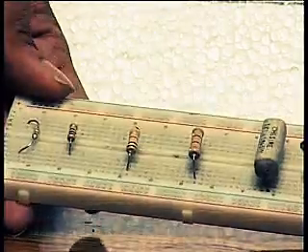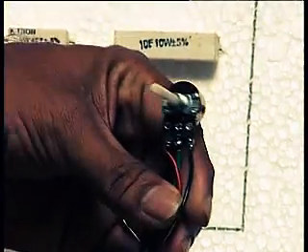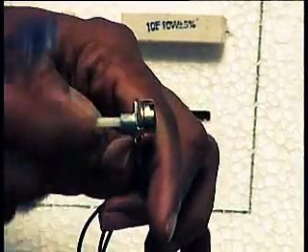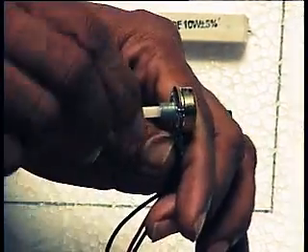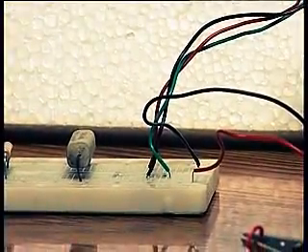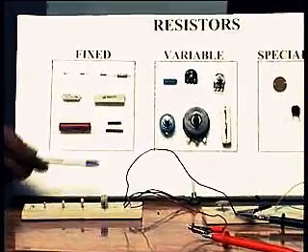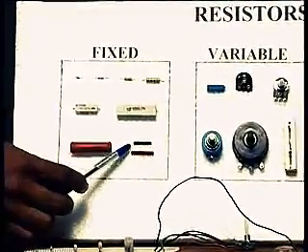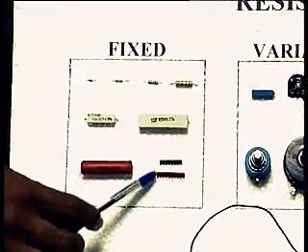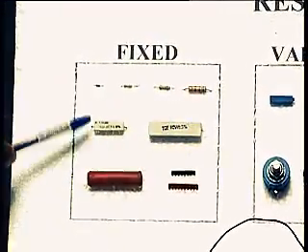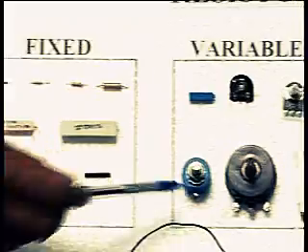because they are used for different higher wattages. Next I have here, for example, a potentiometer that I already mentioned to you. I have a knob here which I can turn, with which I can vary the value of the resistance. So you have 3 leads here. I can measure the resistance using a multimeter. Here I have a number of fixed resistors, as I already showed you. These are actually chip resistors or single in line resistors. These are different wattages.